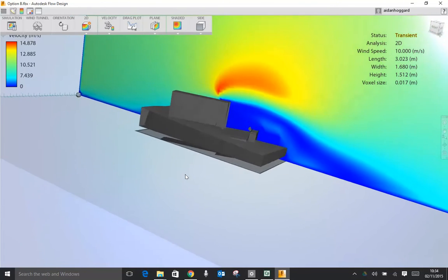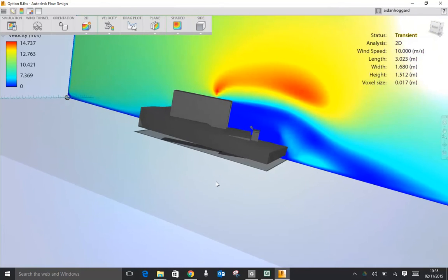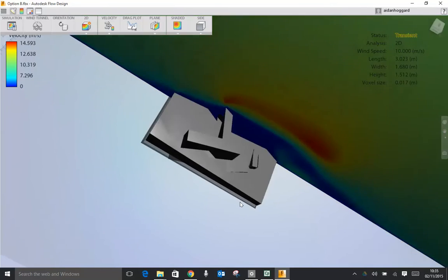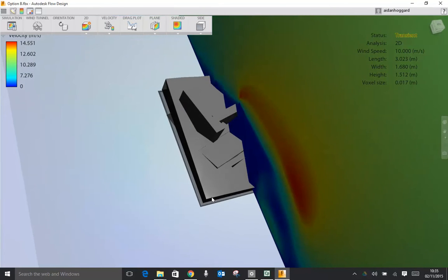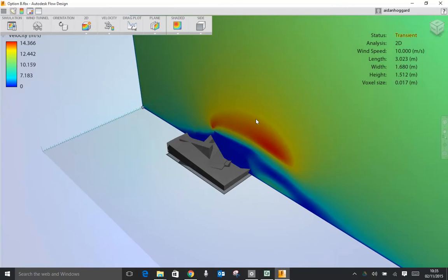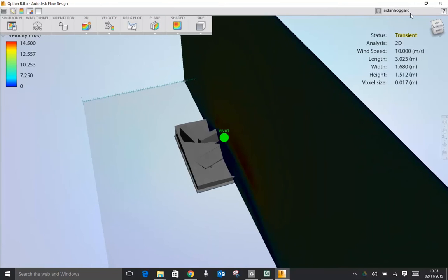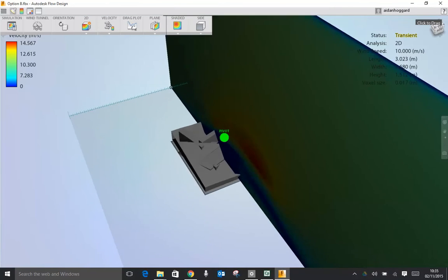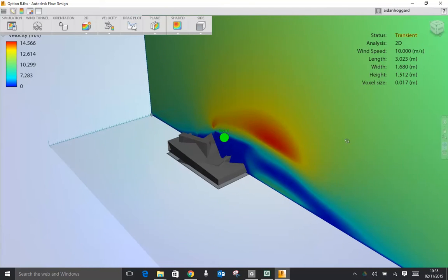Then also you've got your normal mouse controls, but slightly frustrating, it doesn't use exactly the same controls as Revit. So panning is slightly different, it's the left mouse. And also, the reason I don't use my mouse in Flow Design, what tends to happen, you end up with your model on its side because it does not constrain it to a vertical axis, which is quite frustrating. So I tend to navigate my model using either the Viewcube up here, because that will always keep your verticals vertical, or the pivot tool around here. Okay.